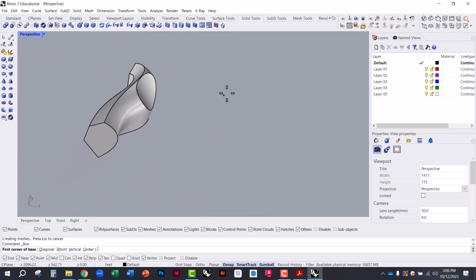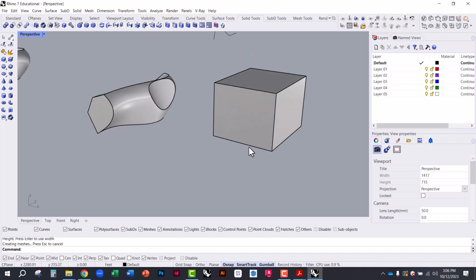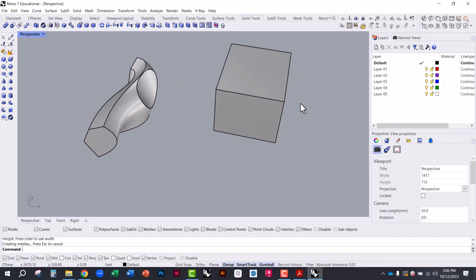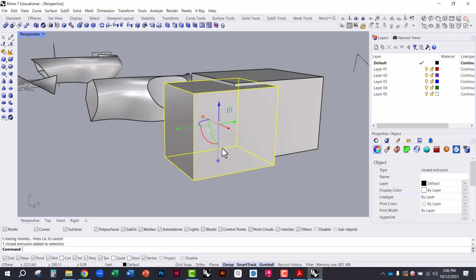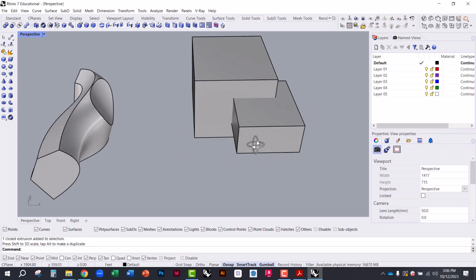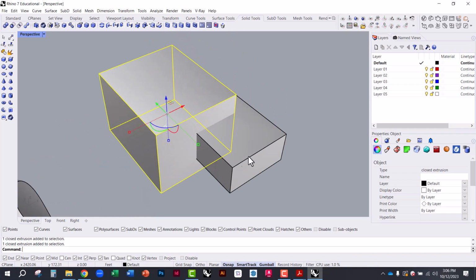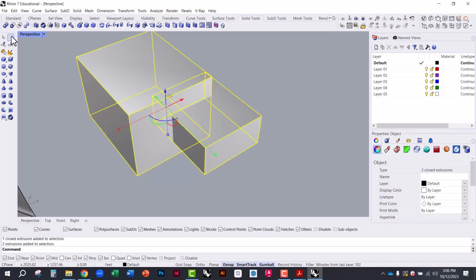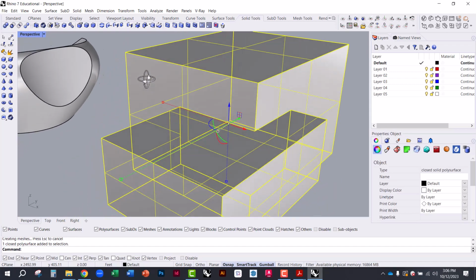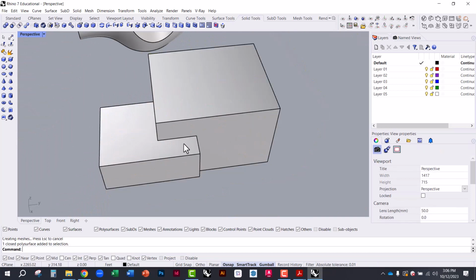So if I have, for example, a box, and if I wanted to repeat a command, you can always hit spacebar or hit enter and it'll repeat it. Right, so if I have these two boxes and I manipulate them, right now these are two independent things. If I want this to be one merged geometry that's completely enclosed, I can select both of these and go to this Boolean union. It's going to add those two geometries together. And so now this is one thing, one poly surface.